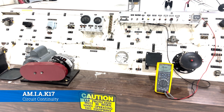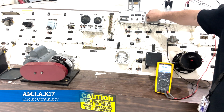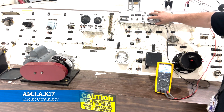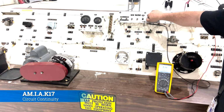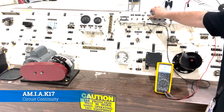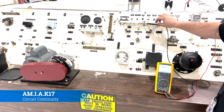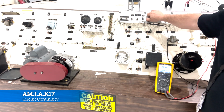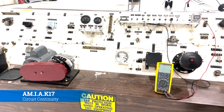Okay, here we have a circuit breaker that is ringing. We're going to pull that circuit breaker, and you can see that it goes to an open line. The ring stops. Push the circuit breaker back in, and the ring comes back. This is a basic troubleshooting technique that you'll do 1,000 times. You'll have a plug pulled, your meter hooked up to it, and somebody pushing the circuit breakers in and out in the cockpit to try to figure out where the break in the line is.